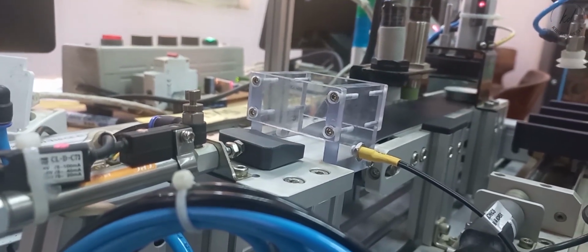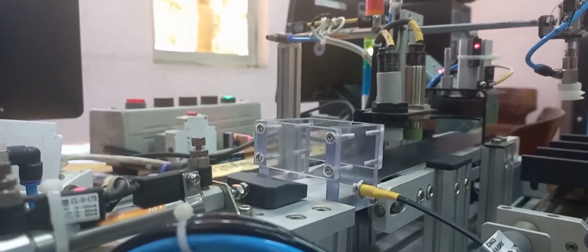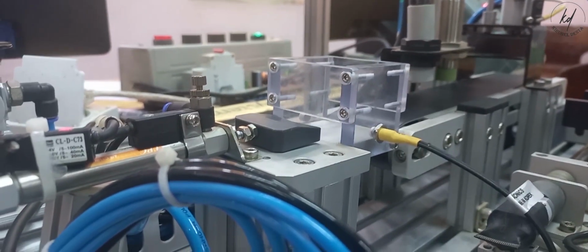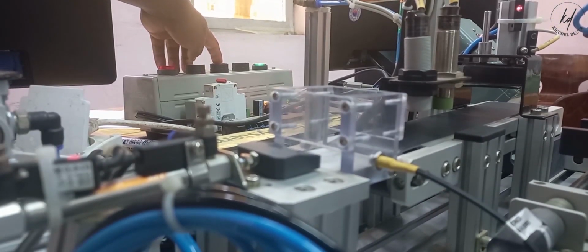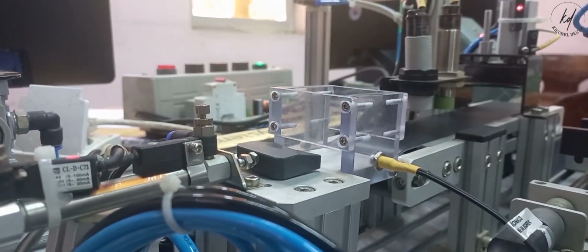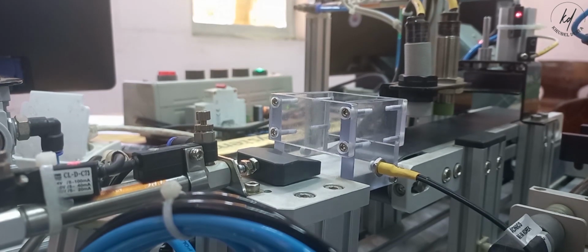That would help the supply solenoid valve to activate, and the previously seen event would occur again. As we press the push button and there is nothing in front of the magazine sensor, only the green indicator lamp blinks for about half a second and it awaits any object to be inserted.